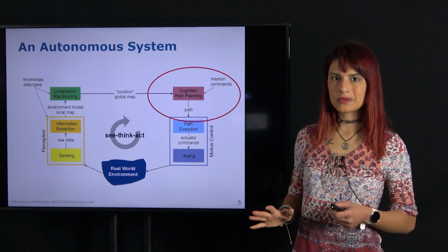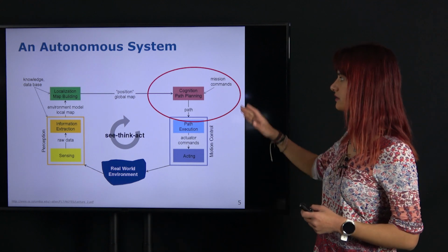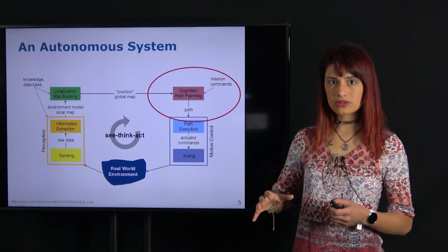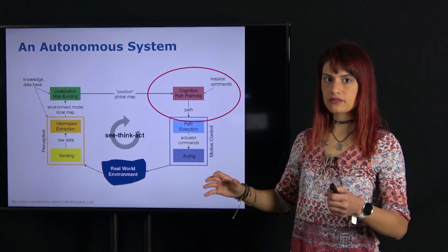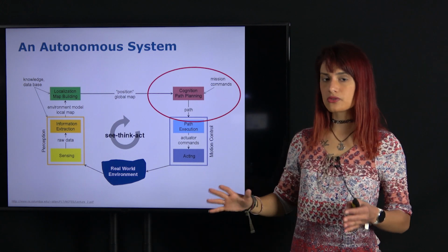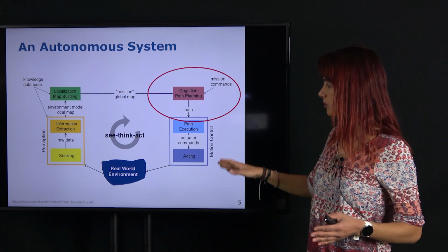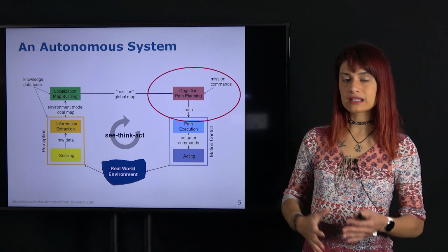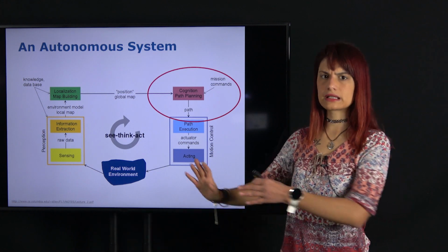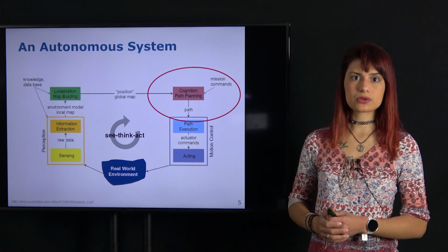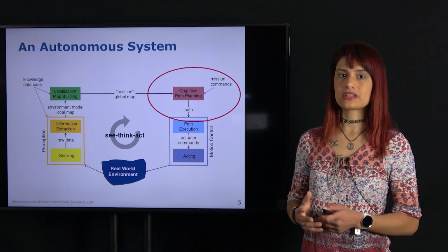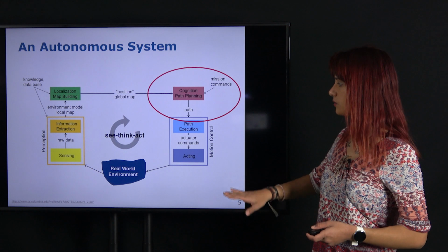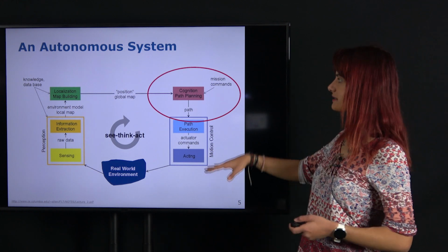One distinction to make here, just to avoid confusion, is the difference between planning and control. Whereas planning is associated with finding that particular path in the environment that we want the robot to actually execute, the control block is responsible for interfacing with the real world and converting that path into commands that we can then send to the robot's actuators and motors so that it physically moves. In other words, control is a more low-level task than planning.